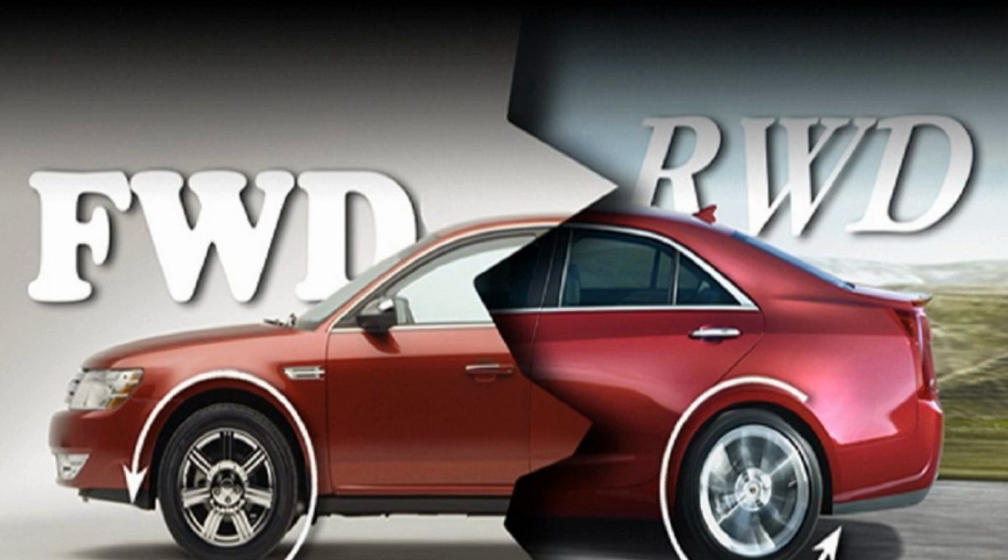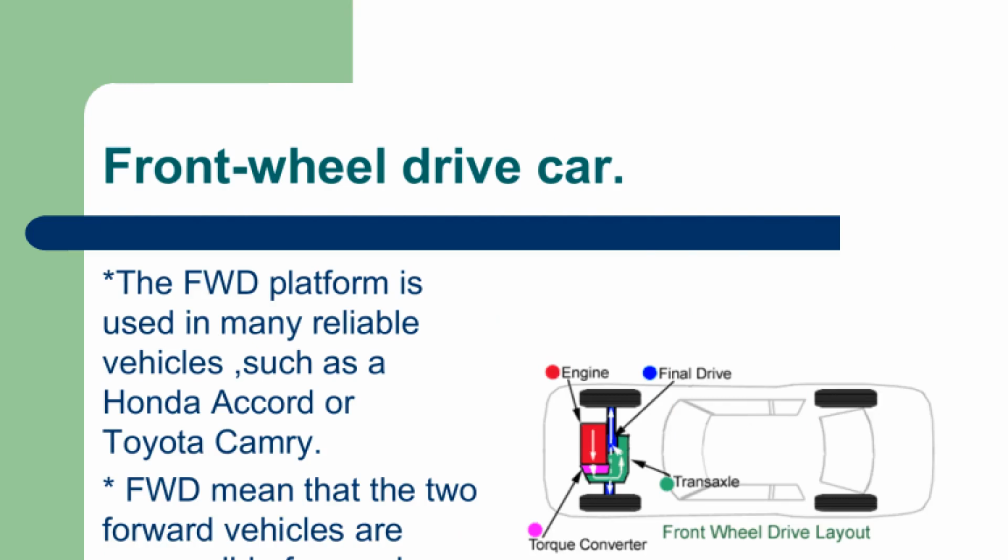Advantages: better axle weight distribution because the rear-wheel drive vehicle has a longitudinal engine layout. This weight distribution improves handling on dry pavement and also helps tires wear more evenly. More space in the engine compartment. This is again facilitated by the longitudinal location of the engine. This solution allows you to install a larger engine in the car. That is why this type of drive is used for sports or executive cars with large capacity engines.